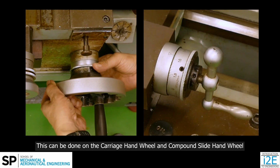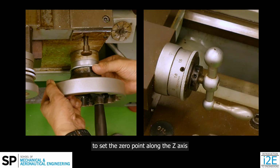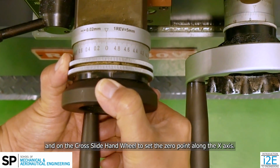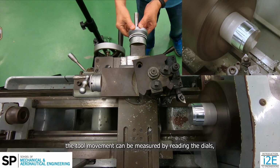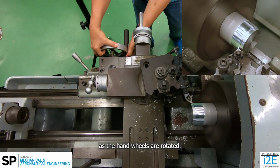This can be done on the carriage handwheel and compound slide handwheel to set the 0 point along the Z-axis, and on the cross slide handwheel to set the 0 point along the X-axis. After the datums are set, the tool movement can be measured by reading the dials, as the handwheels are rotated.